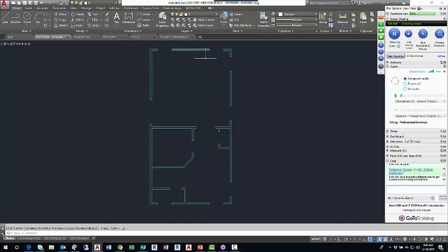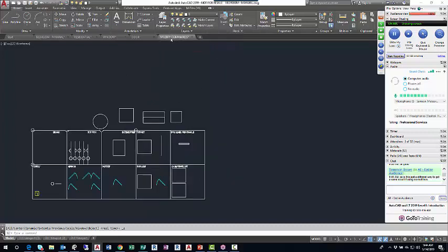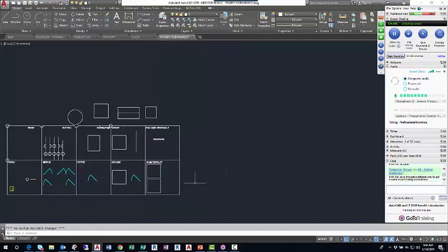So because of the desire to draw things like this, people will use the polyline command. I'll go back to modify commands, and I'm going to create that rectangle. I'll go rectangle, left click the first corner, and then in the XY window of dynamic input I'll type in 16 feet 6, typed as 16'6". I don't need to put the hyphen between the feet and the inches, and I don't need to put the inch mark.